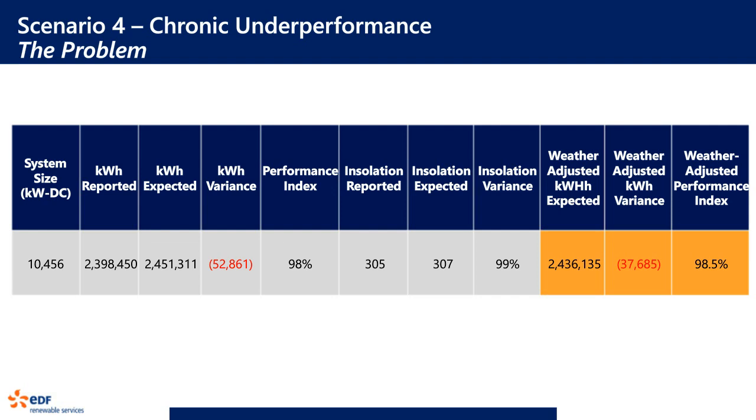So at this point, we start digging even farther into the issue. Start comparing inverter to inverter performance ratio analysis, both intraday and interday. Start comparing signals on the recombiner boxes of the home runs. After all of that, we were still not finding an obvious answer.